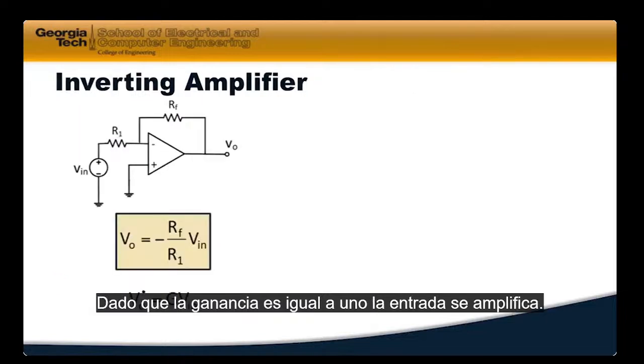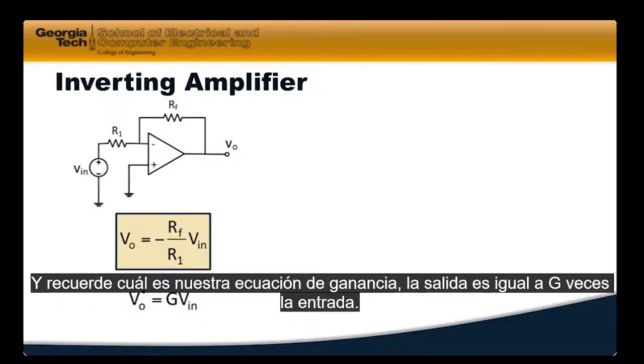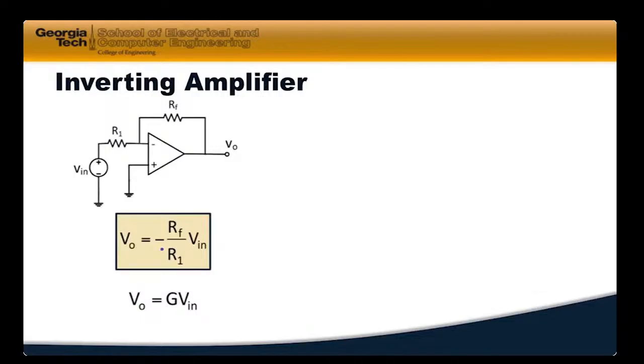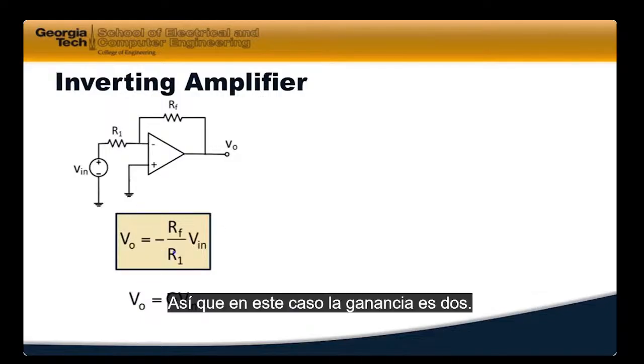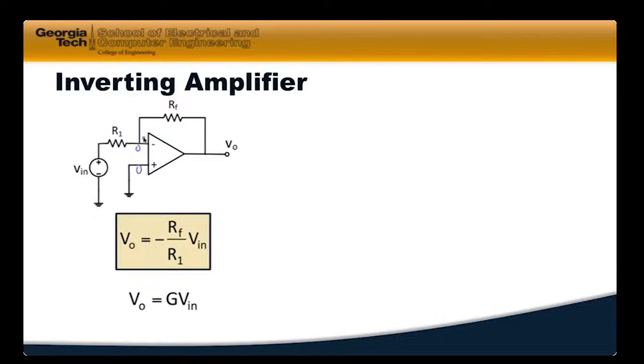So this now is a different configuration. It's an inverting amplifier. The reason we call it inverting is because I've got a negative sign in here. So I want to do the same thing we did last time to derive this input-output relationship by going back to these assumptions. With the assumptions, again, I have 0 current going in and 0 voltage drop here. Since this is ground, that's 0 volts, and this voltage drop is 0. So again, this is 0 right here.